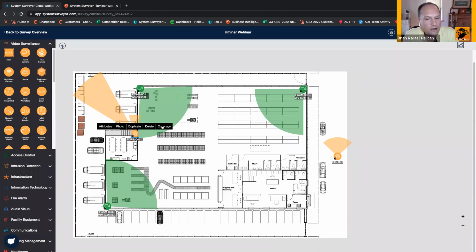So in this case, usually we're defining cameras and the field of view based on some specific design criteria. If you're using video analytics, your analytics vendor is going to tell you we need so many pixels on target, or we need a scene that's no narrower than X and no wider than Y. So the usual approach is to lay out your cameras based on what you need for pixel density or image quality. And then, as Eddie mentioned, the Iluminar product line comes in a varying number of horizontal coverage widths, and then power levels to hit longer and longer distances. So my usual approach when designing projects is to lay out my cameras first, like you did here, and then find the Iluminar product that most closely matches the camera field of view.